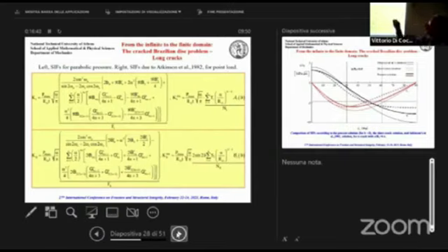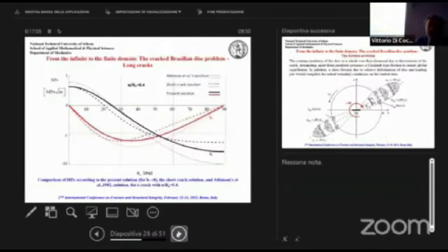You can see here the predictions for the stress intensity factors and those by Atkinson. Exclude the term in parentheses, which are the normalized factors, and which is much more complicated in our case. We accepted the actual loading condition, which is parabolic and not a point load, as accepted by Atkinson. We obtain results which, to our surprise, are very close to each other, even for long cracks. You can see here an example with a crack equal to 40%. And the agreement between our solution and that of Atkinson is close enough. Only the short crack solution is far from the predictions for extreme geometry.